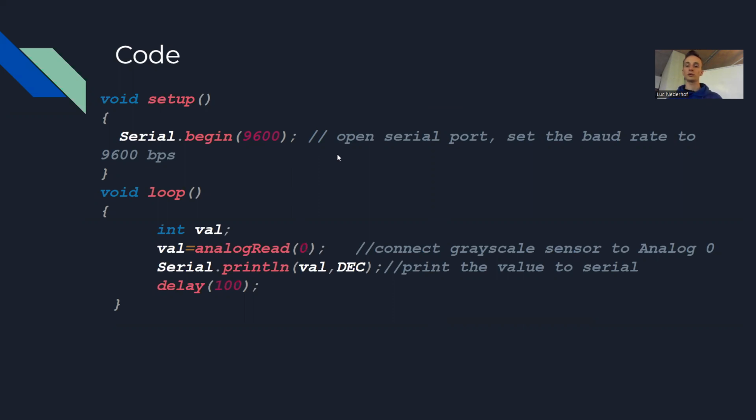You have to initialize serial communication. It is not on by default. When you set it to 9600, you can actually see the data and read the data straight off the sensors if you make it print. The reason that we start our serial communication up here is because we want to print our value down here. And again, we use that Serial handle to do that.